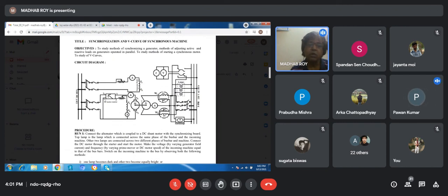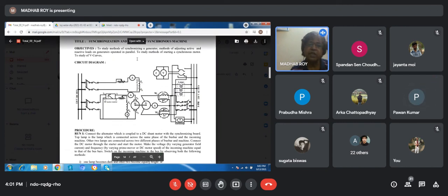Now, when the tube light is connected, in a tube light we cannot see the 0 point. Can you see the tube light at a 0 point? Because the tube light is carrying AC current, there should be some zero glow also, that means a dark point. But we cannot see it because of persistence of vision.